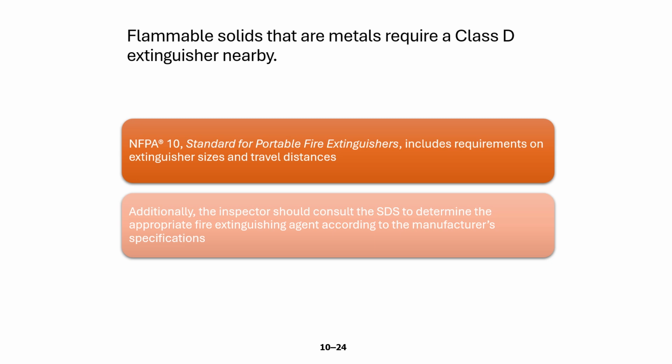Flammable solids that are metals require the placement of a Class D fire extinguisher close to the hazard. When we look at NFPA 10, the standard for portable fire extinguishers, we have to understand as inspectors what those requirements are, not only for the extinguisher size, but the travel distance. That is, visible and accessible, how much do you need, and how far do I have to travel?